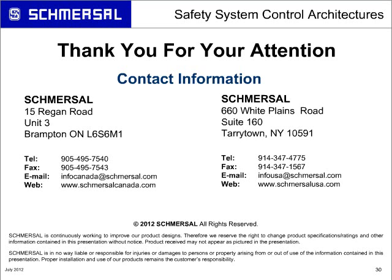From category 2, 3, and 4, there is monitoring aspects to it, so you do need to have that feedback loop to determine those external devices. Now, if the load of the machine is small enough that the safety relay can handle, well, the feedback loop is internal to the safety monitoring relay.